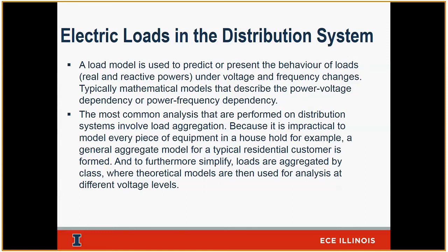So yeah, we rely on the zip models specifically. That's the constant impedance, constant current, and constant power that you're talking about. And those are basic coefficients of what each of the equipment behind these classes would look like. So again, if I look at a house, right? The house will have computers, refrigerators, an oven. I know the equipment that typically exists inside a house. I will have a zip model for each one of these components, right?